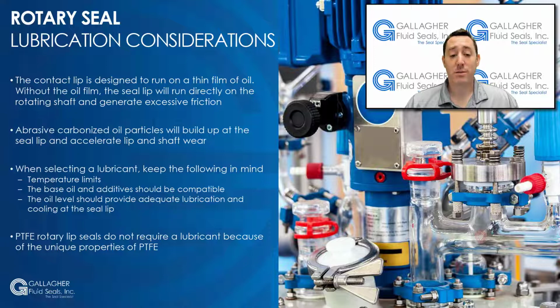If the underlip temperature exceeds the lubricant rating, carbonization of the oil will occur. Abrasive carbonized oil particles will build up at the seal lip and accelerate lip and shaft wear. As the oil film becomes less than optimal, the lip friction increases, as does lip wear.